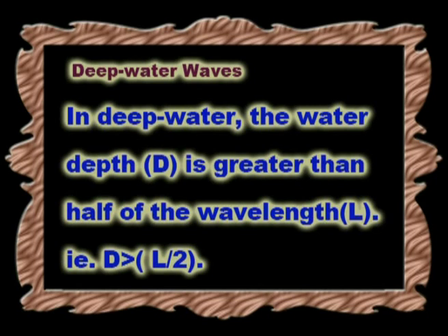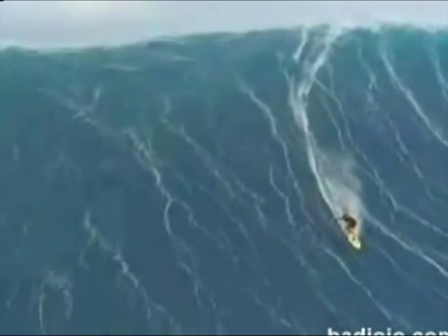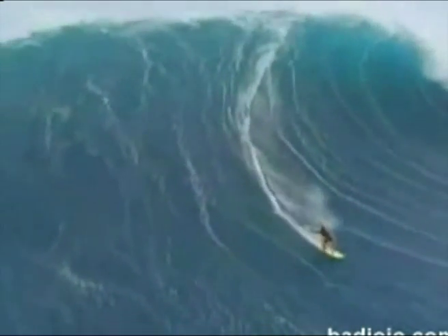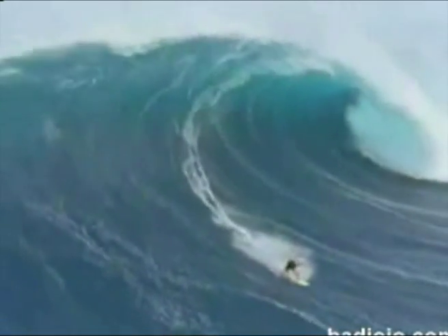The characteristics of waves differ with reference to deep and shallow water masses. Let us see the differences between deep water waves and shallow water waves. The deep water waves. In deep waters, the water depth is greater than half of the wavelength, that is, d is greater than L/2. So, deep water waves travel across the ocean in which the depth of water is greater than one half of the wavelength. All wind generated oceanic waves moving across the oceans are deep ocean waves.